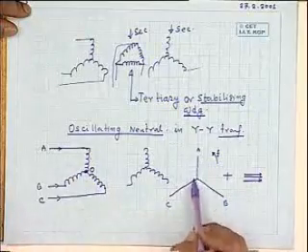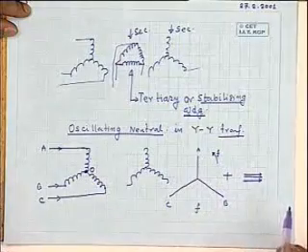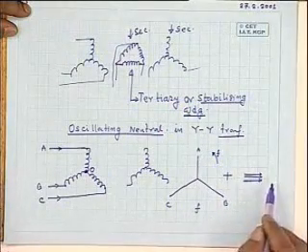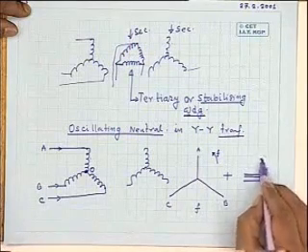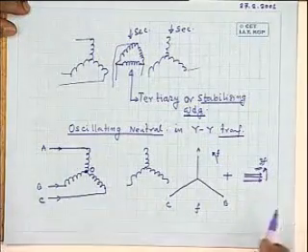Suppose in the windings, what are the voltage phasors present? The fundamental component frequency and third harmonic voltages. And the third harmonic voltages are co-phasal, so I have shown it like this. But they will rotate at what frequency? 3f. In the phasor diagram, you do like this.